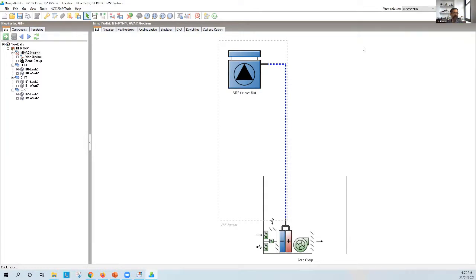You can do it, any sort of VRF, and get some sort of cooling. Usually you'll find that they overcool the space in milder conditions, and people are very uncomfortable. They don't do dehumidification very well, so if it's humid, the system will not give you very nice conditions inside. But these are all well-known problems.